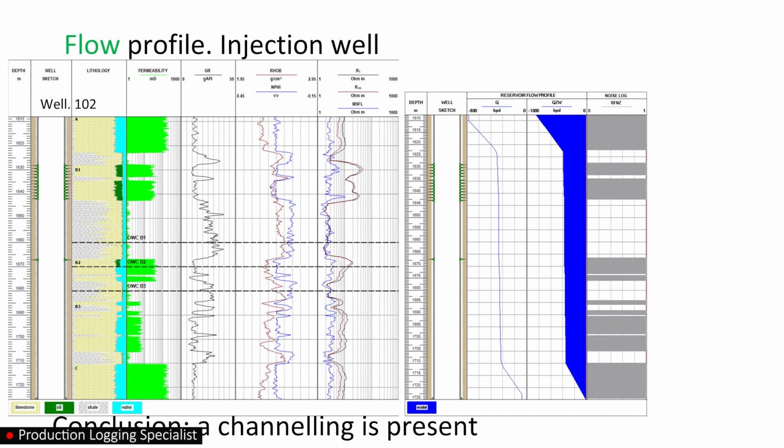Therefore, if we perform remedial jobs on these 5 wells, and the injection pressure does not increase above the point where it causes cement stone destruction, then the efficiency of the pressure support system will significantly increase, as all the injected water will flow into the target formations.